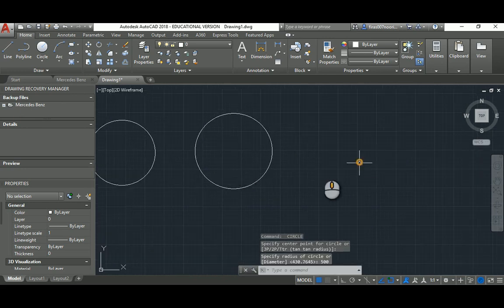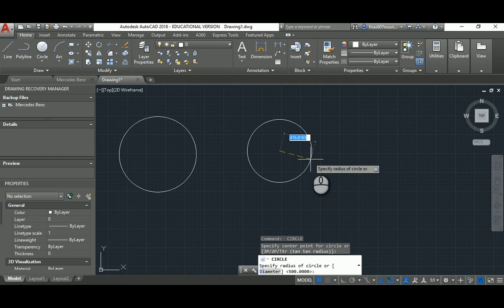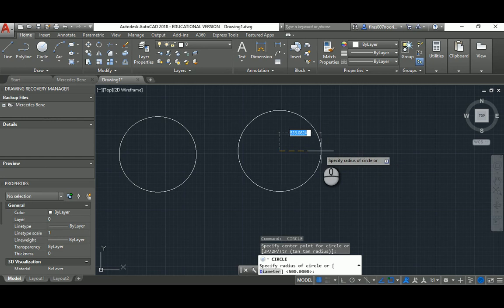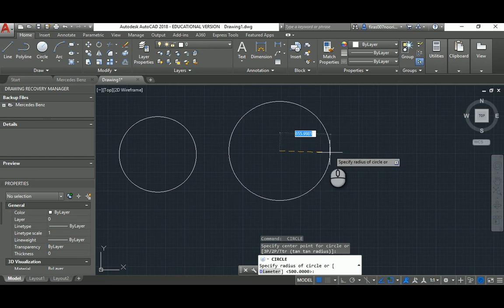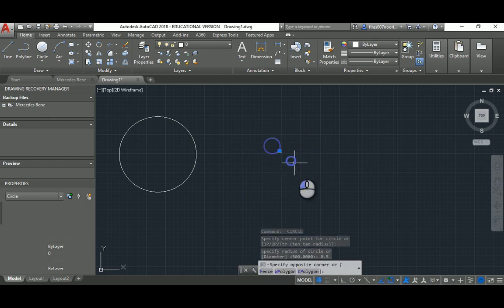Be aware not to fall into the same trap that we talked about, how we fail in AutoCAD, by usually drawing things too small or too big. So when you move your hand, if you are intending to draw freely or based on some number in your brain or in a document you want to take from, and you want to draw something like 0.5, have a look at the circle you are drawing, like it's 600 meters. So if you want to make something 0.5 and you hit space and you don't see it, you don't need to freak out, it's here, it's very small.